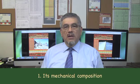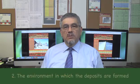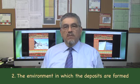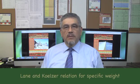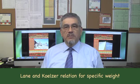The factors influencing the specific weight of a sediment deposit are: 1. Its mechanical composition. 2. The environment in which the deposits are formed. And 3. Time. The specific weight of coarse materials such as boulders, gravel, and coarse sand changes very little with time. However, fine materials such as silts and clays may have initial specific weights that are only a fraction of their ultimate value.